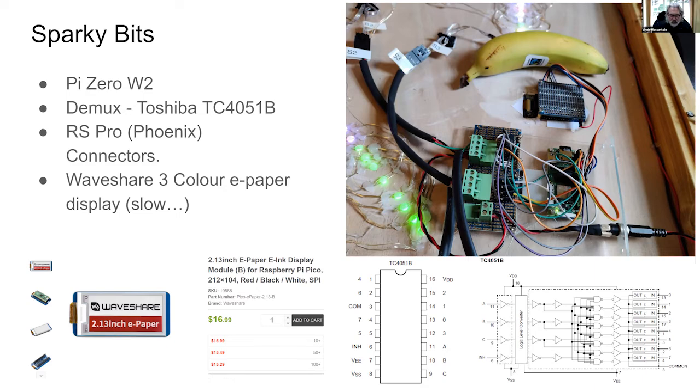The lights I'm using are almost standard NeoPixels. You send them a code and it displays the color that you asked for. Oh. So do they each have an address? Yeah, they each have an address. But it talks standard NeoPixel though, so you just send them the byte codes that you want. So you send three bytes for RGB. That sorts itself out. So as far as you can tell from a programming point of view, they're just standard NeoPixels, but they're not.